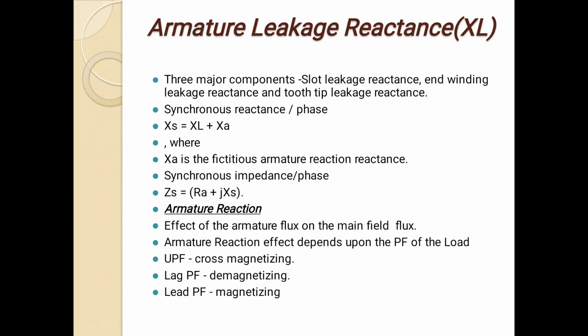The armature leakage reactance XL has major components: slot leakage reactance, winding leakage reactance, tooth tip leakage reactance. Synchronous reactance XS is equal to XL plus XA, where XA is the armature reaction reactance. The synchronous impedance ZS is equal to RA plus jXS.